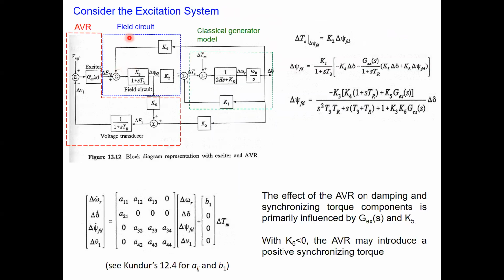So next part, when you consider the exciter circuit, how will you obtain the field voltage to the generator rotor? That will be from another source, and that source is your exciter. It is the exciter which will provide a field voltage to the field circuit of the generator to build up the voltage across the generator terminal.